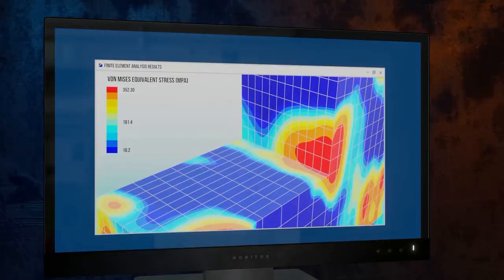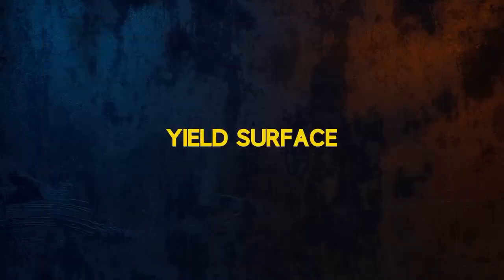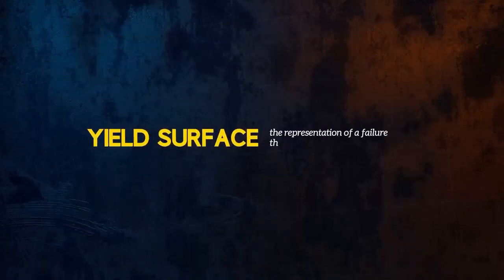When comparing failure theories, it can be useful to plot their yield surfaces. A yield surface is the representation of a failure theory in the principal stress space, which sounds more complicated than it actually is. To keep things simple, let's start by considering a plane stress case, where one of the three principal stresses is equal to 0.